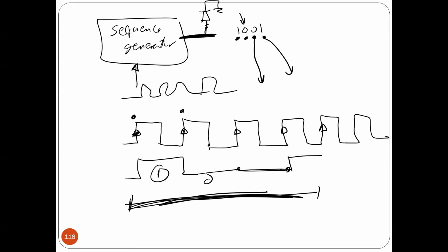If you make the clock very fast, you will see the LED on all the time, because our eyes cannot capture very rapid changes, and even the hardware itself, like an LED, cannot turn on and off very fast. So if you make the clock 1 hertz, every bit lasts for 1 second, which you can notice. You can even make it half a hertz, or less than 1.